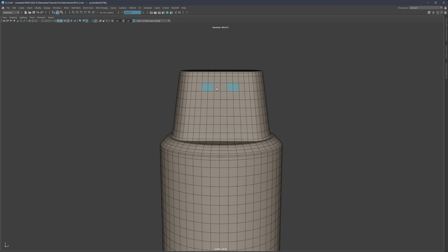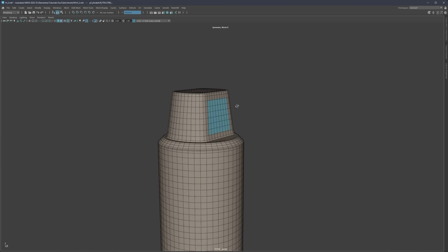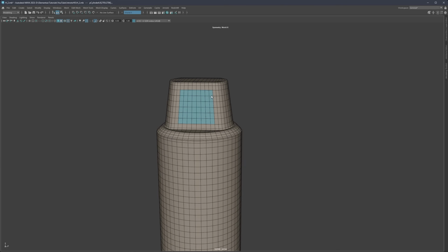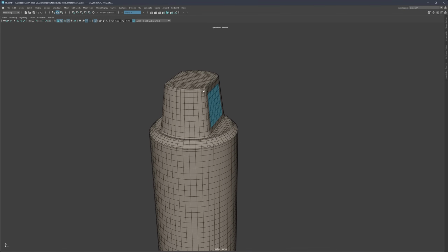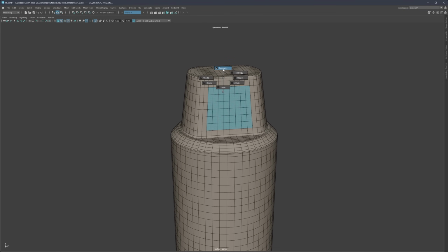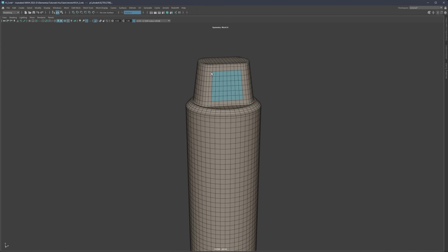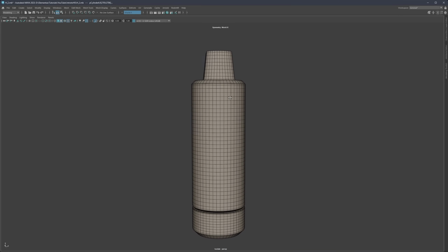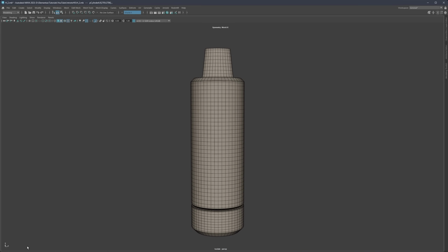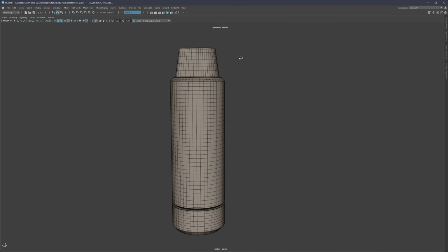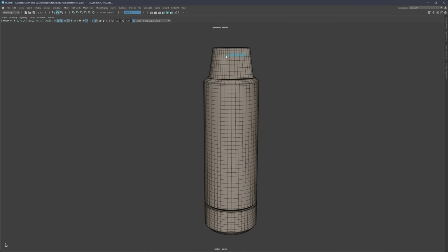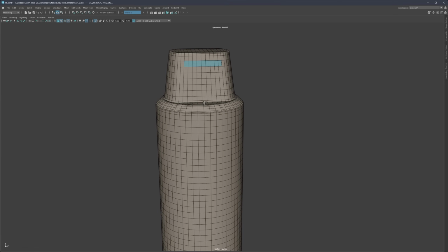So let's now continue, and now we need to create a few things. We need to first create a circle, and let's select all of these parts and try to find something that's working. For example, I would like to do the same thing on the back side. So we have two options. One of them is enabling symmetry on the axes where we have our selection. If you go to the side, this is going to be the Z axis. And if we change from world X to world Z, now whatever we select here is going to be selected on the other side as well.